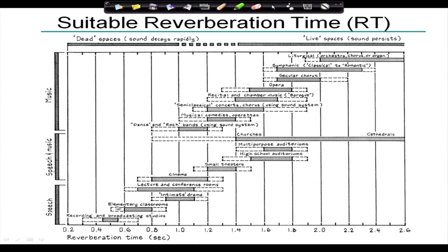Again, there are different kinds of reverberation time; you can read it from that PDF file which will be supplied to you, where different purposes and their reverberation time ranges are given. If it is a cinema, then the reverberation time is 0.8 to 1.2 second. If it is a small theater, it is 1.2 to 1.4. If it is a multipurpose auditorium, the reverberation time is 1.4 to 1.8. So, there are different reverberation times for different purposes, standardized by architecture firms or by the world, readily available.